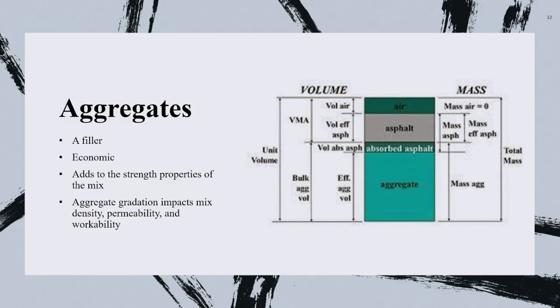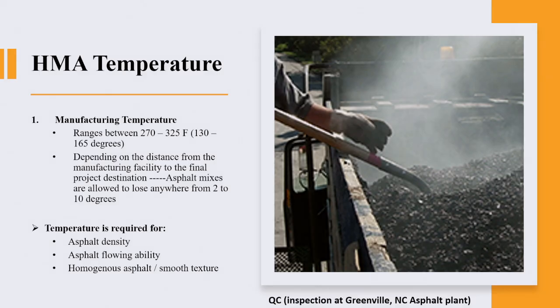You do the same thing here with asphalt. You have to quantify through the kerosene test what is the portion of the asphalt that will be absorbed by the aggregate. And then let's say it's going to be 0.75%. Then if you need 5%, do 5.75. This 0.75 is gone. You're left with the 5% which you were targeting from the very beginning. Otherwise, cracking would happen in no time. So this is an extremely important parameter when it comes to the aggregate gradation and the ability of the aggregate to absorb binder from the mix.